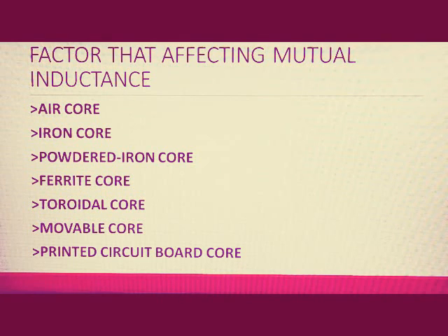Iron core inductors use iron or an alloy for a core. Large values of inductance are possible. Hysteresis and eddy current losses limit iron cores to low frequency, such as power line and audio. Laminated sheet material is often used to reduce eddy current. Soft iron materials such as silicon steel may be used to reduce hysteresis losses.